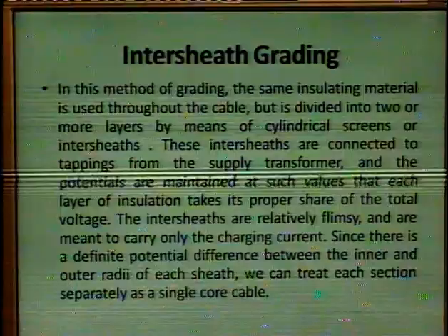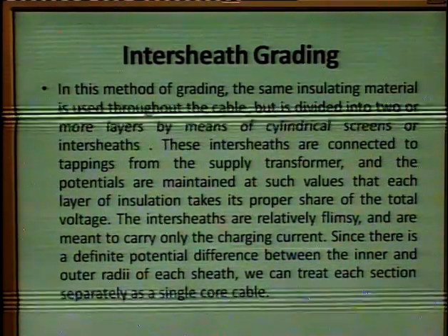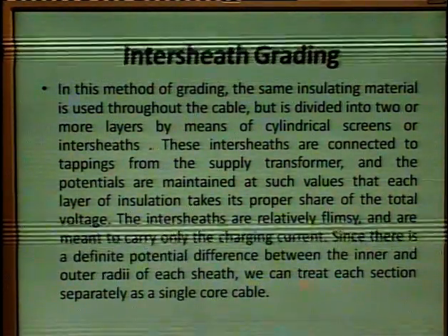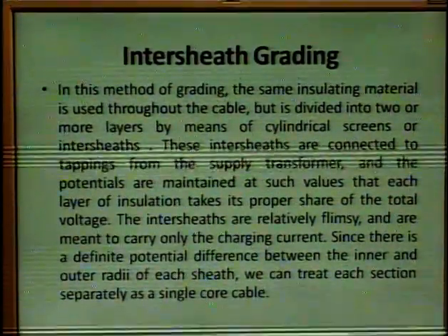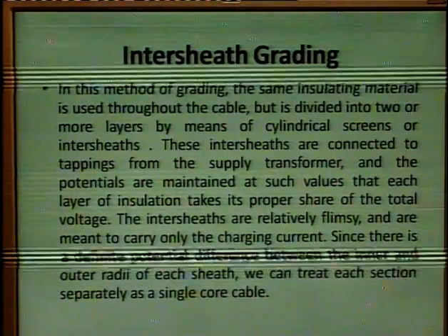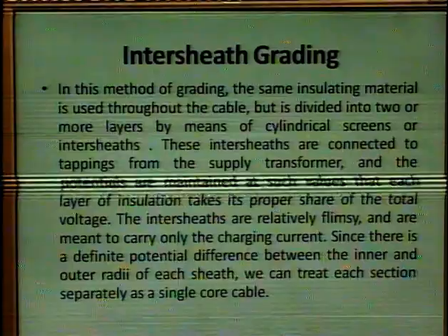These intersheaths are connected to the tappings from the supply transformer, and the potentials are maintained at such values that each layer of insulation takes its proper share of the total voltage.